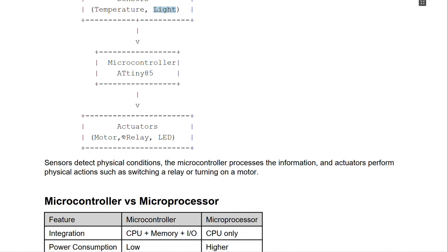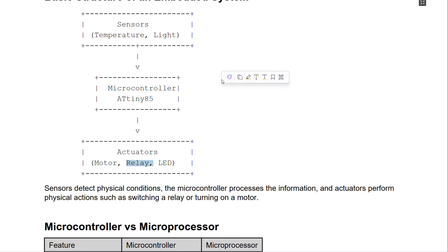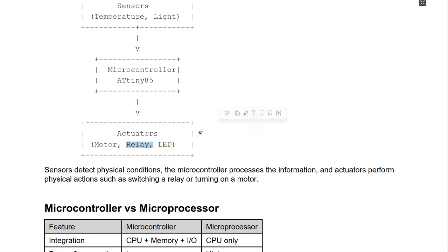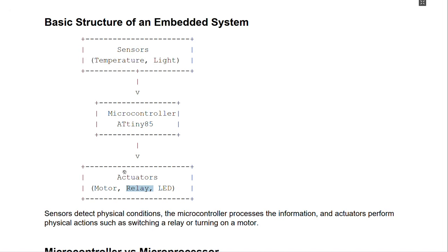So that we have an actuator, let's say a relay. In this case, we have a relay in the energy meter, right? Our UEDCL meters or UMEME meters, I don't know how you choose to call them. We have a relay to reconnect a consumer if they pay, if they have a prepaid subscription, or their subscription expires. They've used all they've paid for so far, and it's time for disconnection. That's when the relay inside the meter unit disconnects the user until they reload again. Then the whole metering process repeats in a countdown fashion.